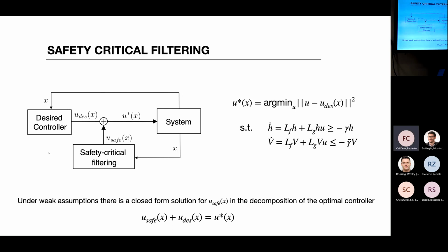To solve at every time step, the optimization problem, which just says, okay, I want my CBF constraint and possibly CLF constraint to be satisfied. And what happens is something like that. Basically, I have a desired control action, and this optimization transforms my desired feedback control into a new feedback control, such that it keeps invariance and stability of the equilibrium. And this is how it is used.